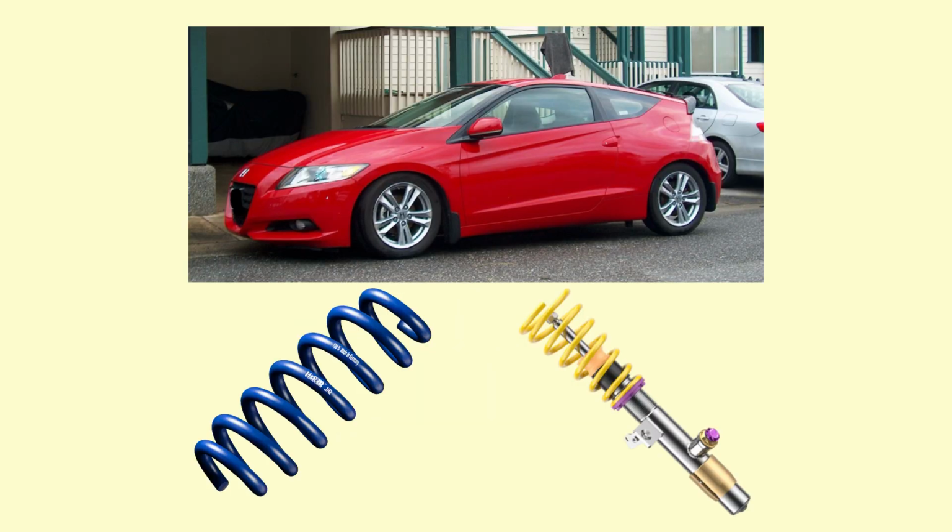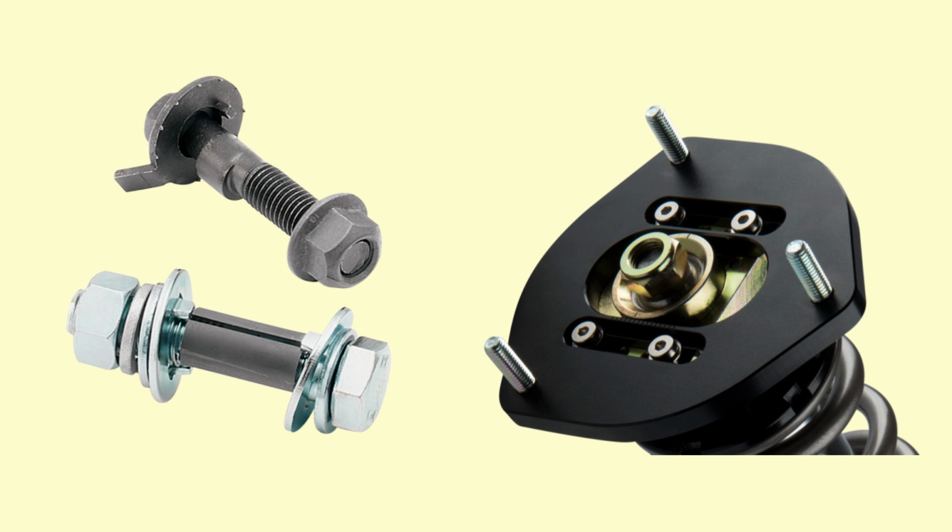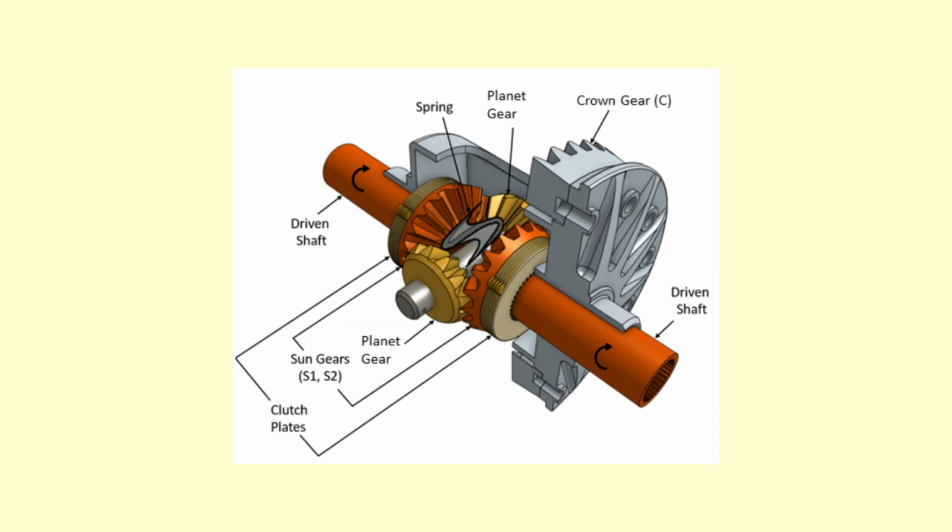To reduce understeer, we can apply some of the same driving techniques and modifications. For weight transfer to induce neutrality in the chassis or even oversteer in the front-heavy FR, we can use either lift-off oversteer or trail braking. For additional grip and understeer reduction, we can use stickier rubber, reduce front ride height, which allows for a lower center of gravity by eliminating excess body roll, though with negative camber in the rear to improve traction during cornering by keeping those rear tyres more planted, and a rear limited-slip differential to ensure the inside rear wheel is not slipping, and that grip between the two rear wheels is evenly distributed.